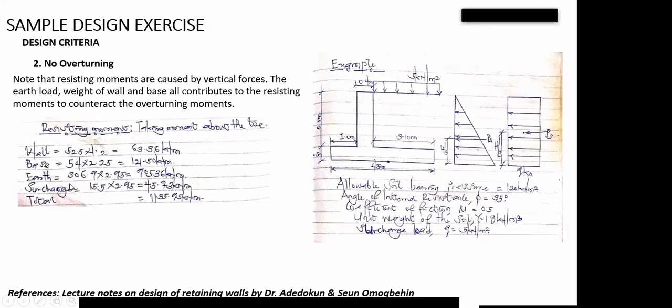But for vertical moments now, for resisting moments, we are considering the vertical what? The vertical effect, that is the weight of the what? Of the earth itself, which we calculated earlier, we got 306.9. Now, the weight will be acting at the center of this 3.1, because this is where your earth is actually sitting, which is 1.55. So if this place is 1.55, 1.55 plus 0.4 plus 1.0. So you can easily say 1.55 plus 1.4. That will give you 2.95.